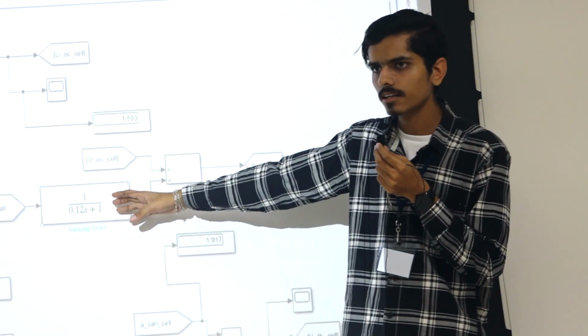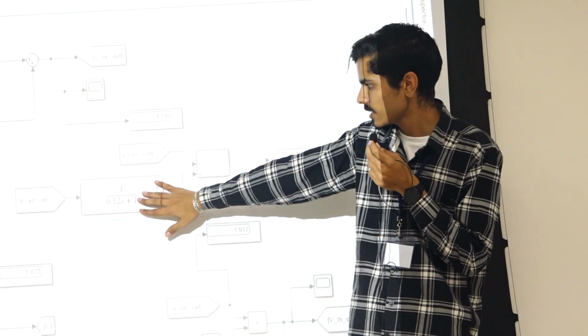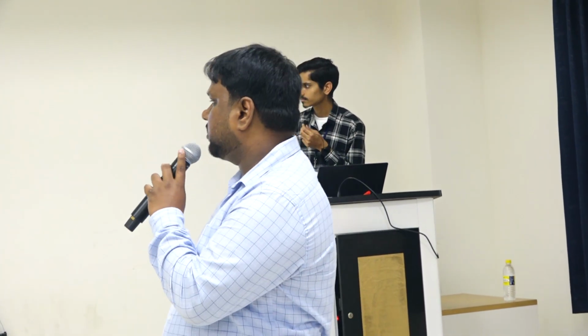But ultimately, it can cause an algebraic loop error in our simulation. So that's why we have to consider it also, of an actual electrolyzer cell. You can see what the double layer capacitance is, and that effect we model in terms of a first order transfer function to give some dynamics. Okay.